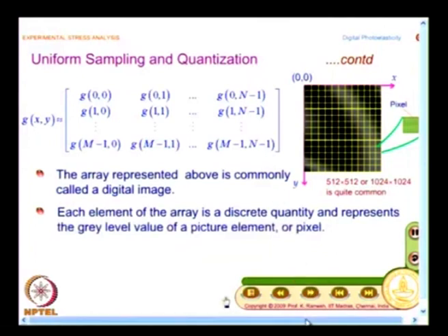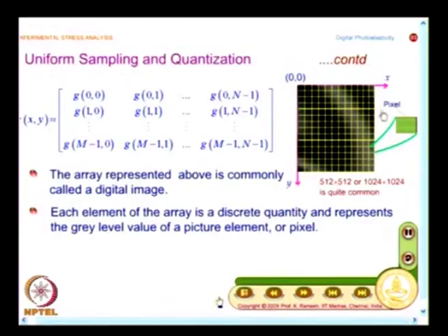and what you will have to keep in mind is, what we call as a pixel is a very small area. By appropriately using a lens, you would be in a position to even go to stress concentration zone and find out, when you have very high fringe density, you have a decent resolution at the camera plane. So, I can have an optical magnification and then enhance the features in stress concentration zone. That is how people solve when you have a very high fringe density, they optically magnify that zone, then take it up in your digital image and appropriately process it.